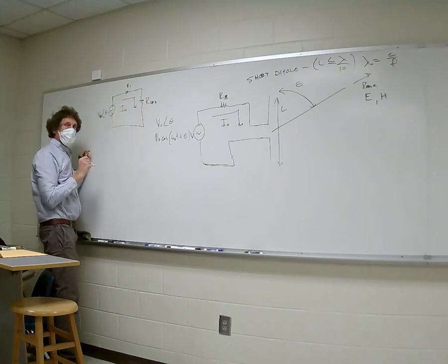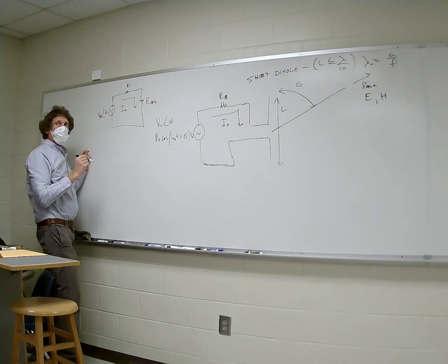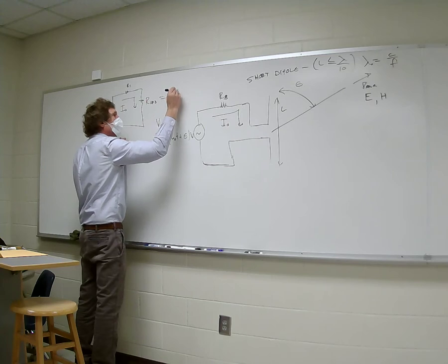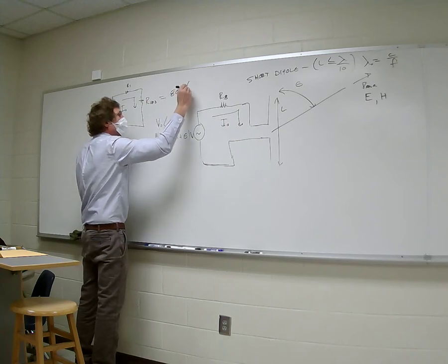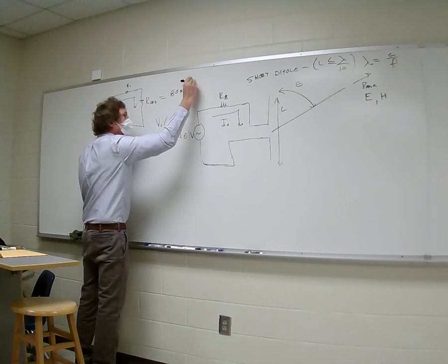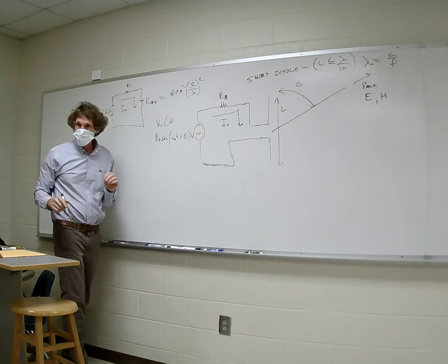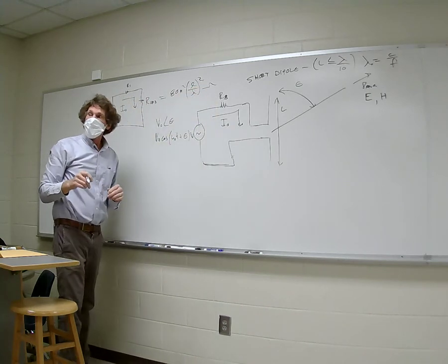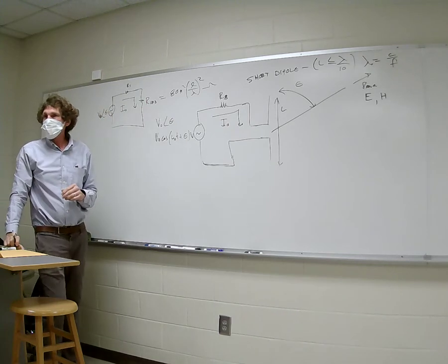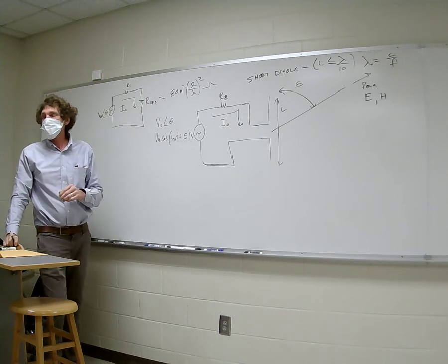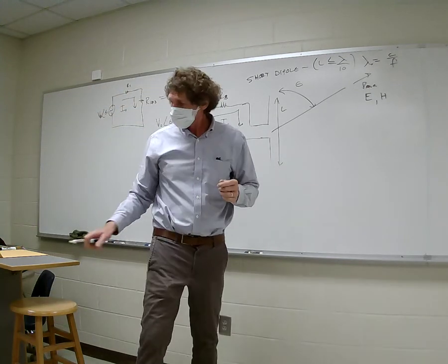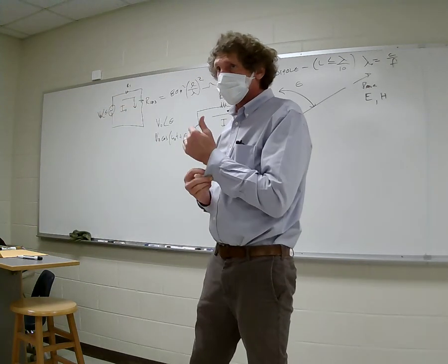All right. Now, if you remember, R radiation for a short dipole was 80 pi squared times L over lambda, squared, in ohms. I would give you this equation. I'm just going through this. If I'm moving too fast, put up a hand. And I know some of you are note takers, and I really appreciate it. You need to let me know if I need to slow down. Is everybody clear on this so far?